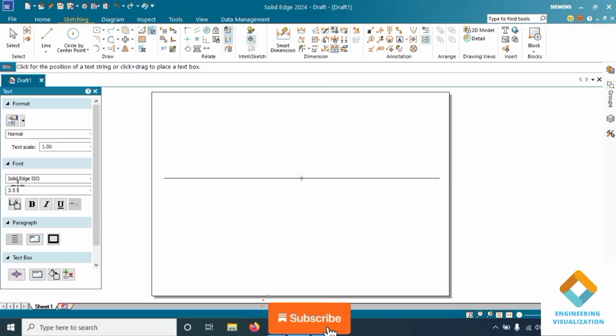So first we'll be drawing an XY line and writing VP and HP. Here the first position will be a circle, but for that circle they have not given any dimensions, but they have mentioned the dimensions for the ellipse, that is major axis 60 mm and minor axis 40 mm. So the major axis of the ellipse will be the same dimension as that of the circle.